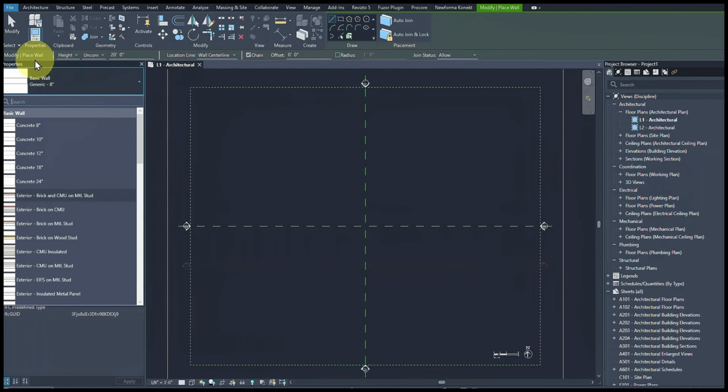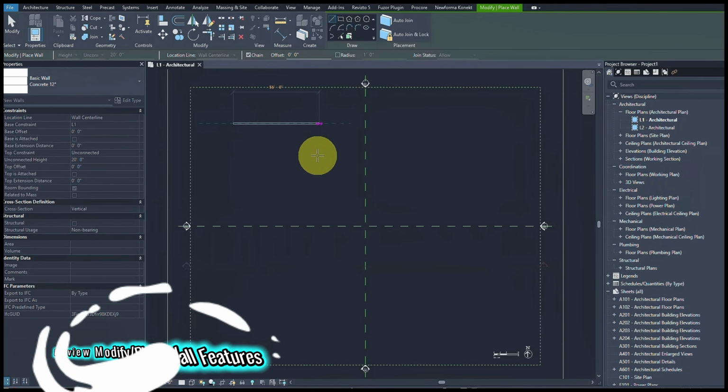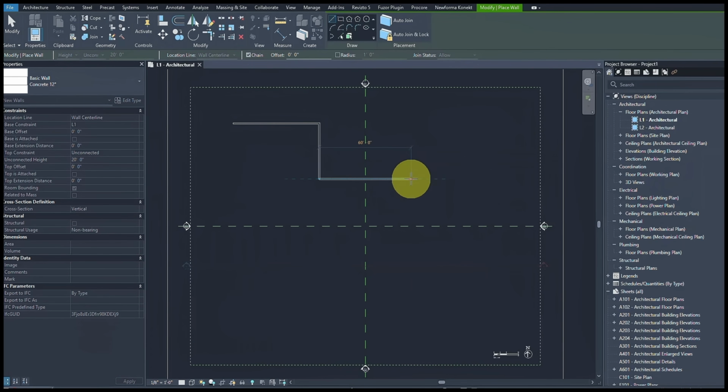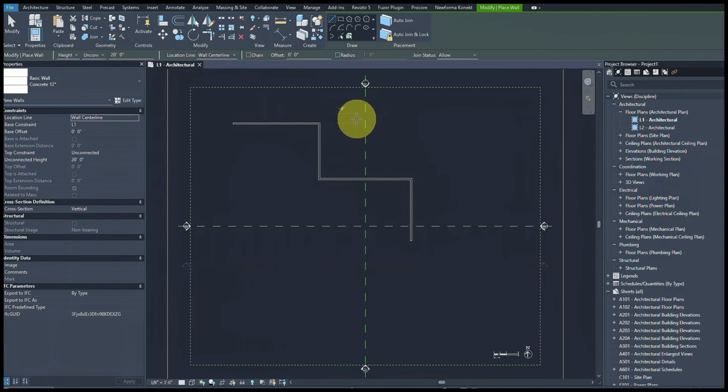One main thing when you select the wall, immediately you can see a few options or features on top, right? I want to first start with the chain. It's a simple one. If I want to select any type of wall and I have the chain on, it means I can just draw everything following each other in a chain. And if you don't want to do the chain, you can uncheck the box, and you're done with the wall and it stops.